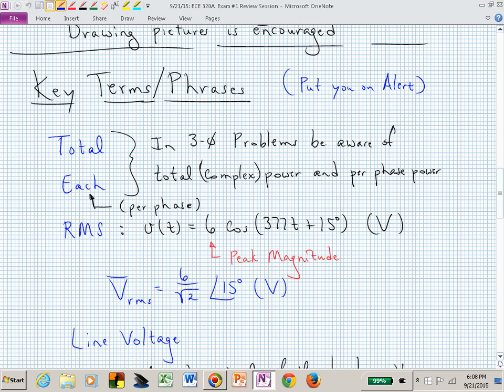That's clear, right? That was one of your homework problems. You had to take the root mean square. You first square the waveform, you take the average of that, or the mean, and then you take the square root of that result. And that's now basically an effective value to replace that complicated waveform. Now you can view it like a constant waveform, and it has the same power absorbing characteristics as that weird waveform might have had.